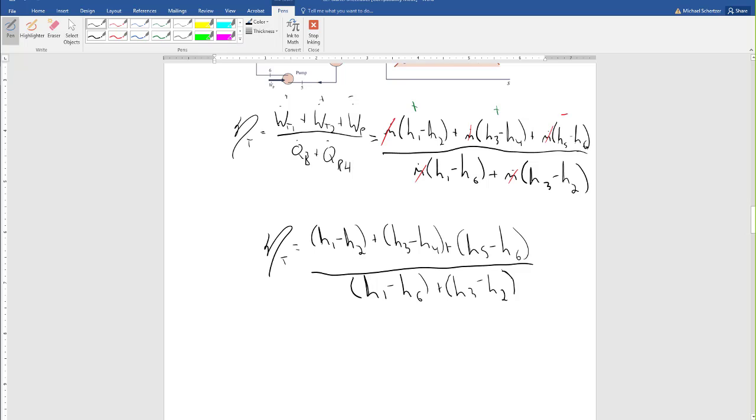The textbook tells you to add the turbine powers and subtract the pump power, but they're going to tell you that the pump power is m dot times h out minus h in. They do that because it's the absolute value of the pump power, but you can't get that expression from the first law. So I don't like to do it the way the textbook does it, because I'm trying to minimize as few things as I can.